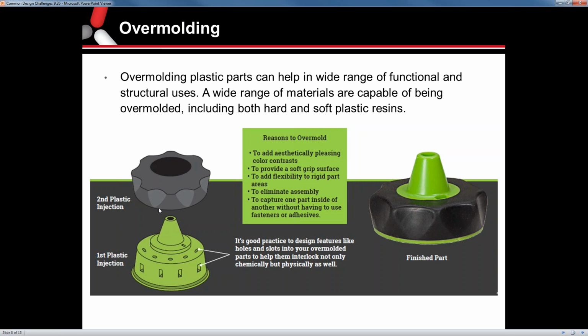And going back to the threads, we had talked a little bit about overmolding threaded inserts. Not necessarily a plastic fill issue, but things we've run into here were inconsistencies on the thread ID. What we do is load these inserts onto a pin or a post that locates it in the tool so that when the plastic flows over, it's in the right position. Sometimes we do contend with lots of inserts that are sent to us for this purpose, and only to find out that some are small, some are large, which creates inconsistencies in the injection process. So that's just something to look out for.